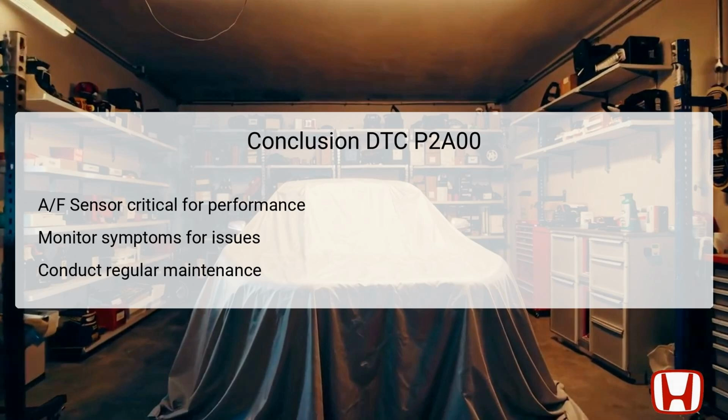Drivers should remain alert to symptoms such as the check engine light, poor fuel efficiency, and potential performance issues, as these signs may indicate a malfunction in the AF sensor system. Conducting thorough troubleshooting steps, from monitoring engine conditions to inspecting and possibly replacing the AF sensor, is essential for resolving this issue effectively. Lastly, engaging in regular preventive maintenance, including routine checks on the sensor and its connections, can help ensure long-term reliability and performance, reducing the risk of future DTC occurrences.